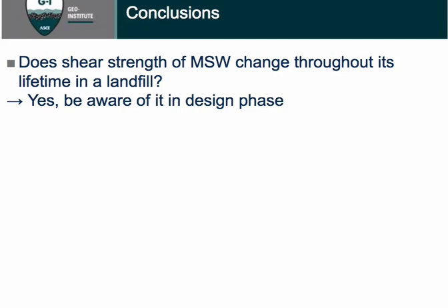The first conclusion is, yes, of course, the shear strength of the municipal solid waste changes throughout its lifetime. We have to be very aware of that, because usually a landfill is designed for decades to centuries. When the waste is in place, it's very hard to retrofit or reinforce it.